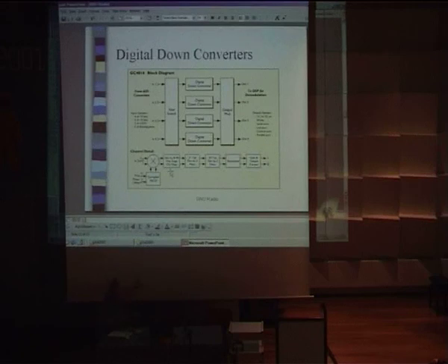And in here, part of the game you want to do is, you've got the signal coming in at, say, 65 million samples per second. This is the data rate up here. And ultimately, what I want for doing my signal processing at baseband is typically something running at about 4 times the symbol rate. So if you look at GSM, the bandwidth is about 200 kilohertz band spacing. You're going to want something like twice that, so 400 kilosamples per second out. So you're fitting 65 million samples per second in, and you're really going to want something in the neighborhood of 400 kilosamples per second out.